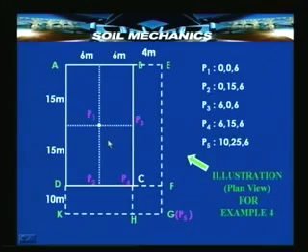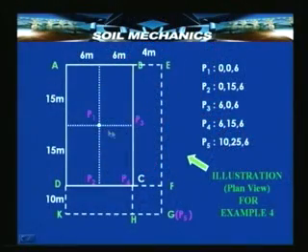then I will get the same influence factor and the same stress, because the other 3 rectangles are also meeting at the same point P1, they have the same dimensions. So, the stress at point P1 can be computed by multiplying by 4 the stress obtained due to one of these 4 rectangles, the dimensions of which are 6 meters in the horizontal x direction and 15 meters in the y direction.